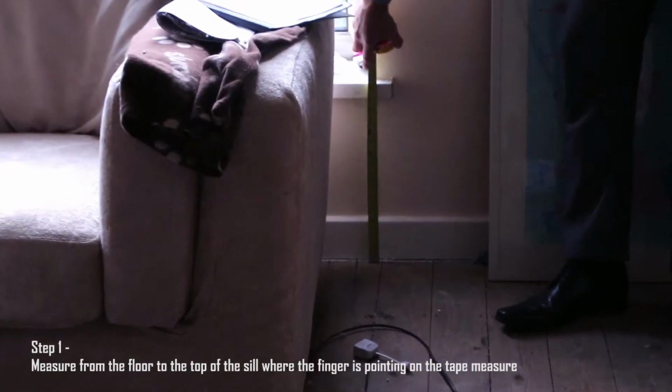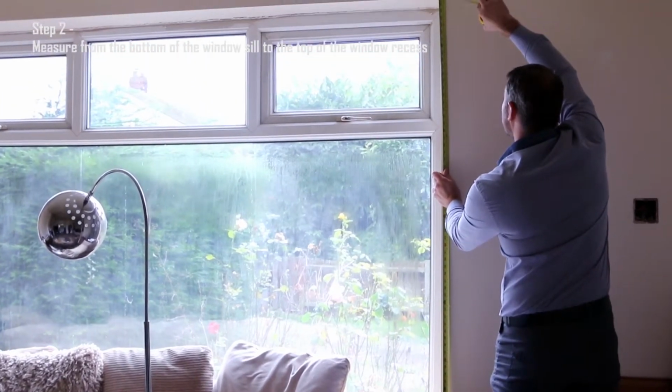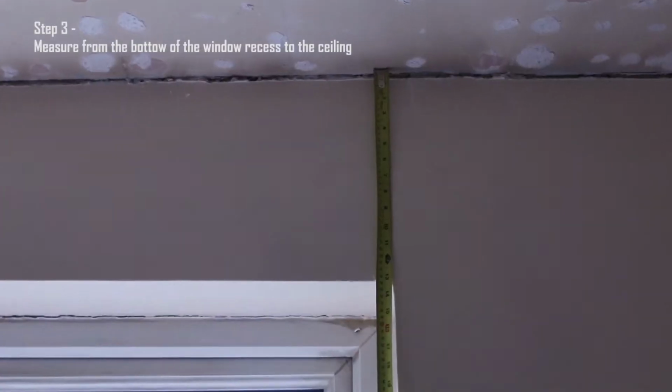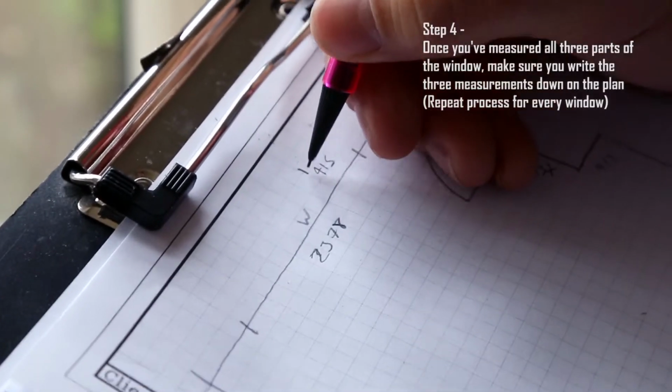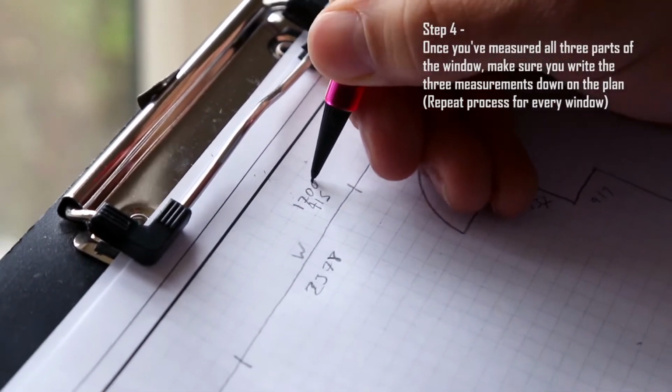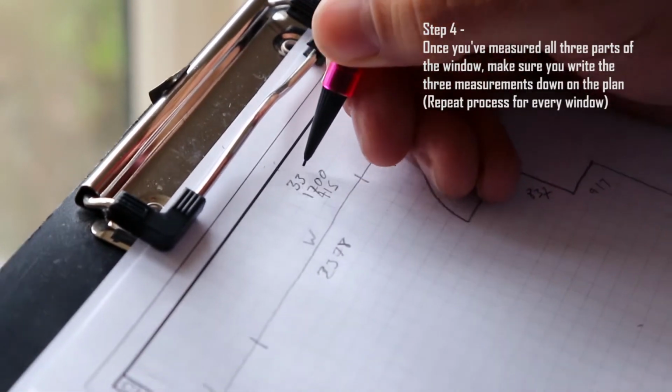When measuring the heights of windows, we need the bottom of the sill to the floor, the height of the window itself, and over the window. Write clearly on the pad 3 heights: underside, window height, overside.